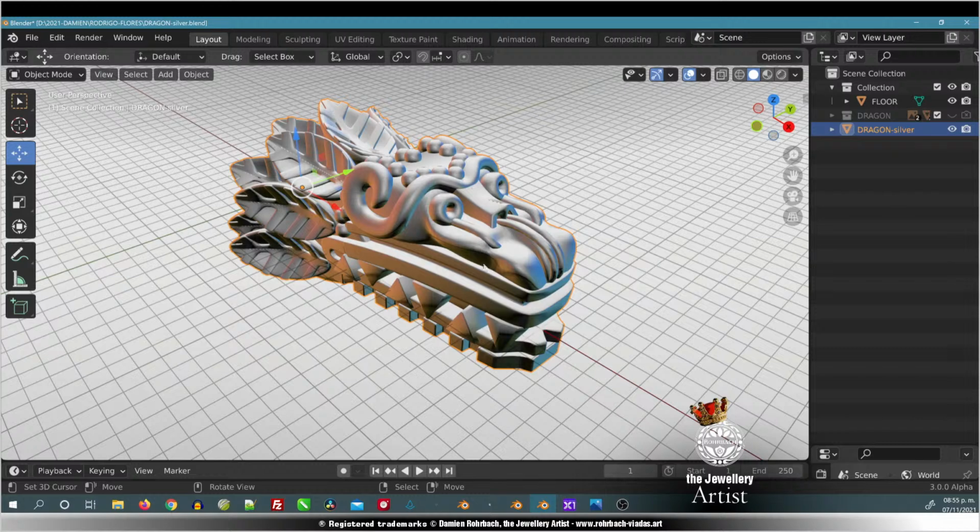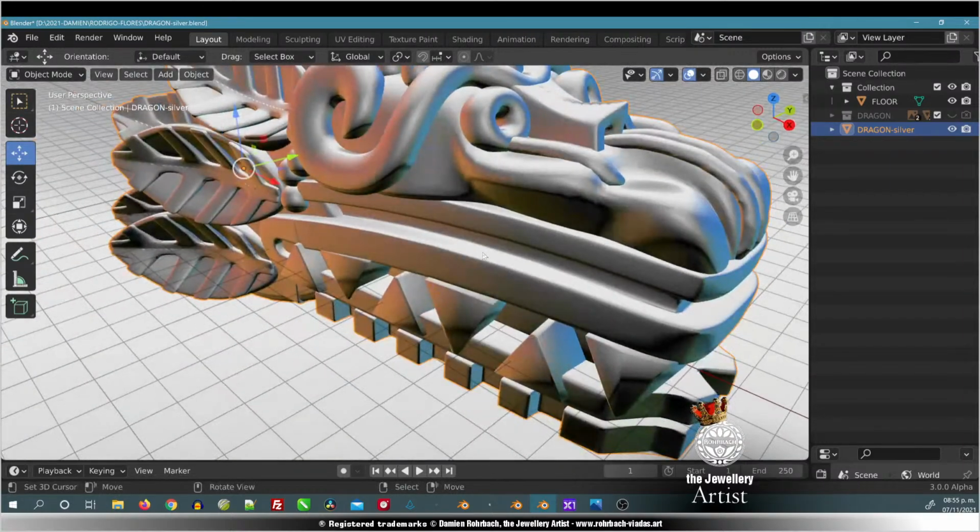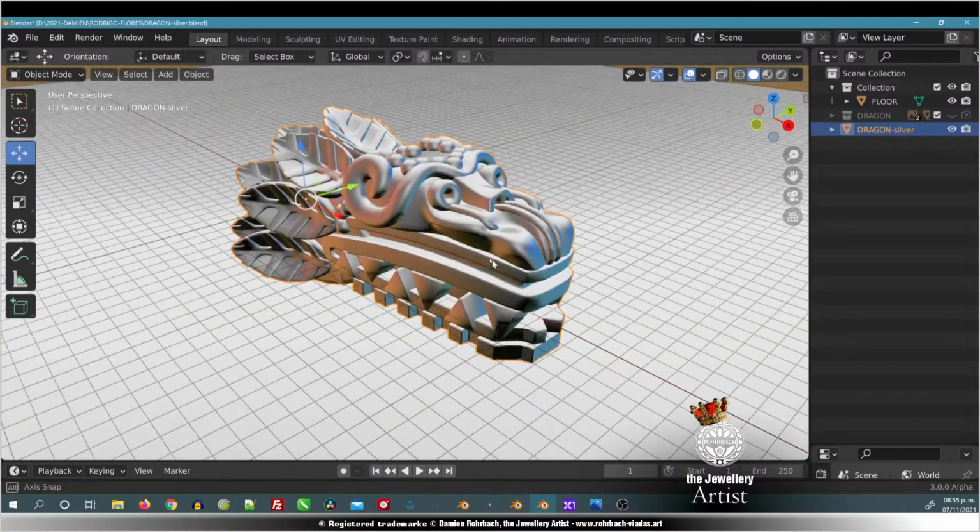Okay, that's another mistake many people make. When you finish the 3D model for 3D printing, never show the renders to the client right away. First, try to make the STL, because some files, the STL is going to be very hard to generate for bad booleans, for bad modeling, for many reasons. You have holes in some meshes. It happens in the best families, it happens to everyone, it happens to me.